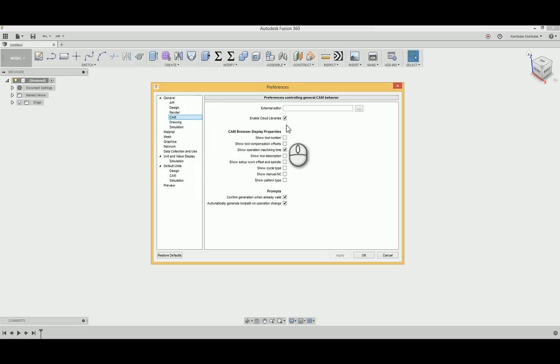Of all of the things that are in these options, there's one that says show manual NC. It's right there. Click that. Make sure that one's clicked off. The other ones, you don't have to duplicate this. Just make sure that one is turned off. And then what I want you to do is just hit apply. Don't hit OK, just apply.